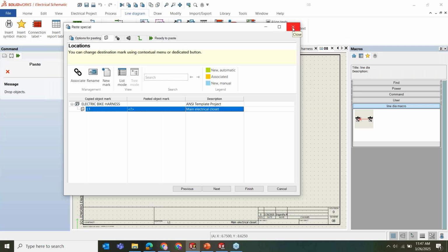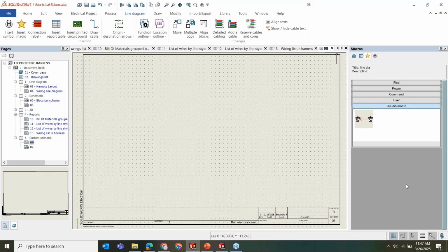We can move it from one page to another page, and we can also place the same type of macro multiple times in the same page. Okay. Now you would be wondering what is different between macros and copy paste, right? With macros, whatever I place here becomes part of one main library. So essentially you're also creating a circuit library. Once you create that circuit library, you can reuse it any number of times you want without any hesitation.